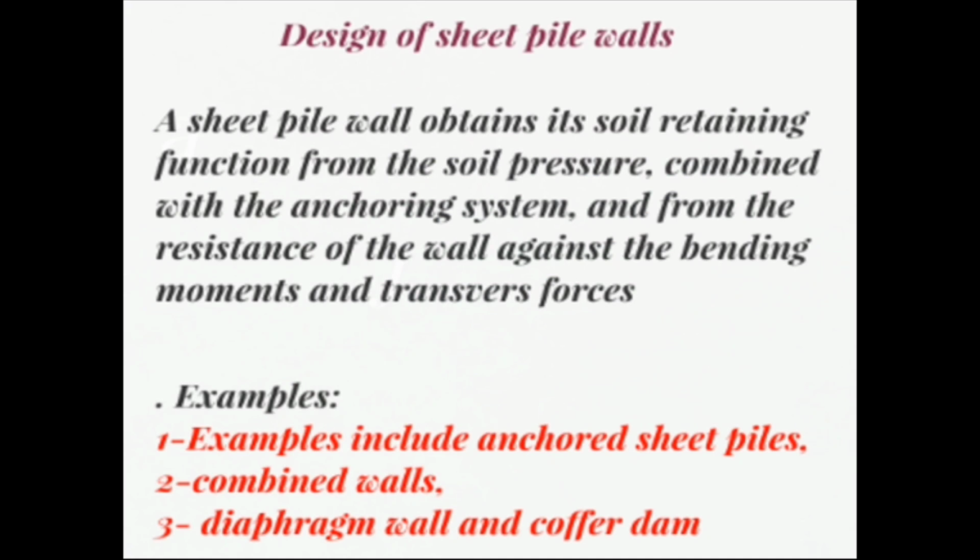Design of sheet pile walls. A sheet pile wall obtains its pressure retaining function from the soil pressure, combined with the anchoring system and from the resistance of the wall against the bending moments and transverse forces.